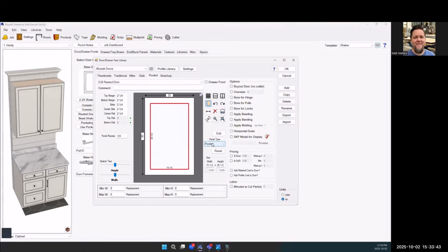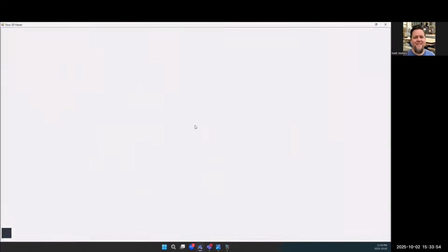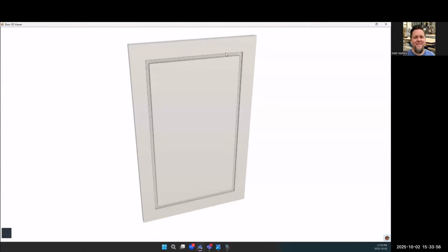And I'm just going to change the panel type to be a one piece. The panel recess, I would just set that to 0. This is not going to come into effect now with this door. All we're doing is we're running a tool path now around the door that your tool group can follow. There's no pocketing included.